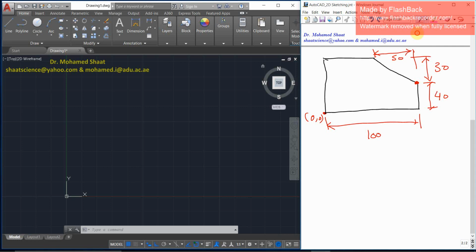This is the practical thing. Practically speaking, in terms of engineering drawing, if you're going to create an engineering drawing for another engineer, you have to represent the dimensions and the details of any inclined line. This is what is preferred in engineering: that we identify the dimensions of the inclined line using horizontal and vertical dimensions. There is another way.